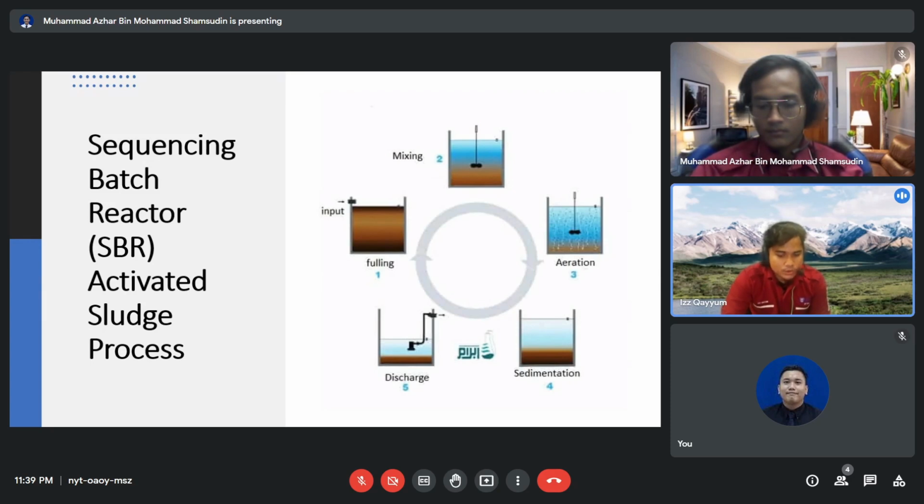Continuous flow systems hold the mass ratio of influent substrate to biomass constant by adjusting return activated sludge flow rates continually as influent flow rate, characteristics, and settling tank underflow concentration vary. After the SBR, the batch of wastewater may flow to an equalization basin where the wastewater flow rate to additional unit processes can be controlled at a determined rate. In some cases, the wastewater is filtered to remove additional solids and then disinfected.